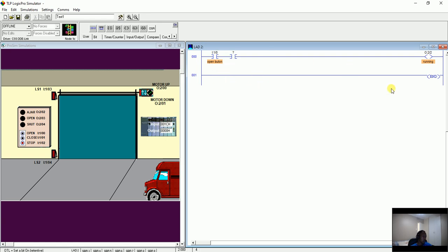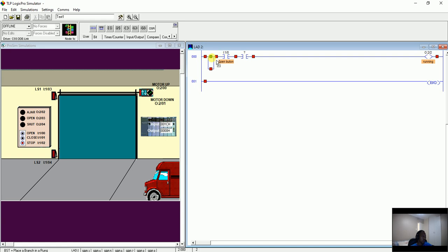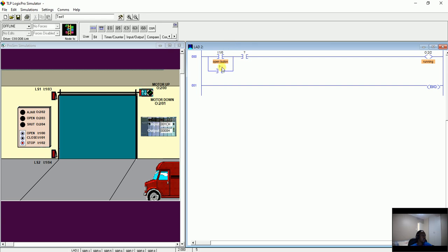We want to say, okay, since I'm running, I should either use the latch as an output, so that I'll unlatch when I press the stop, but I'm going to make it simple for everyone to understand. So here we're going to have start, then whilst this one is running, whilst this one is energized, it's going to latch through this one here.